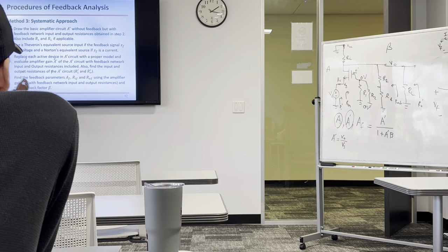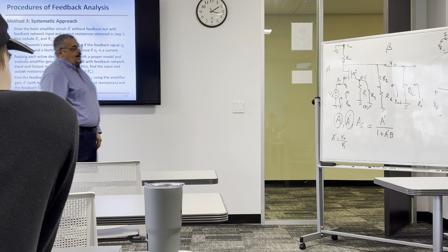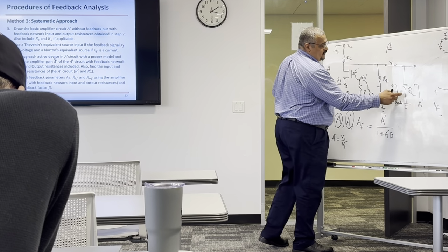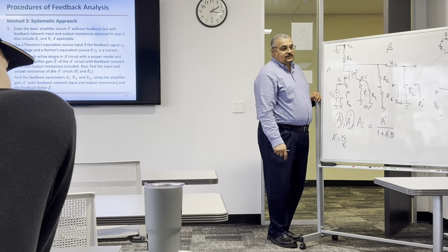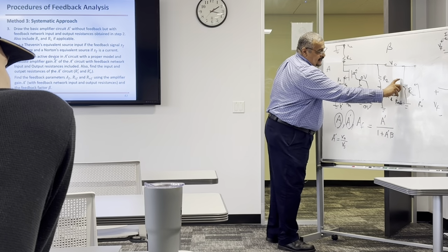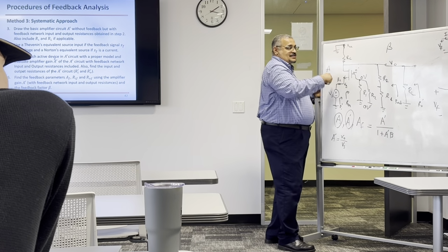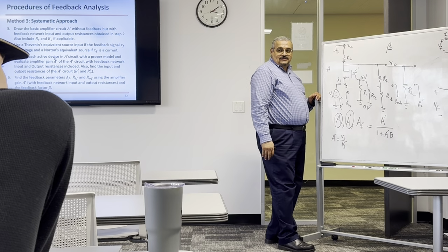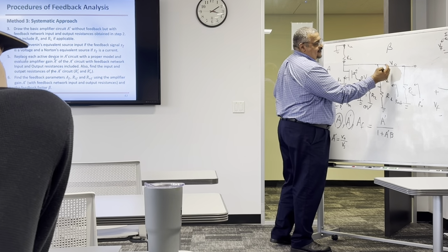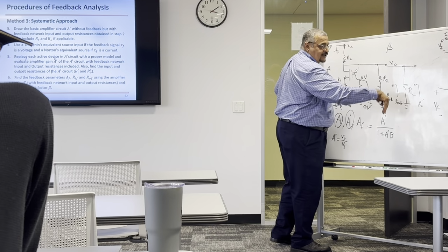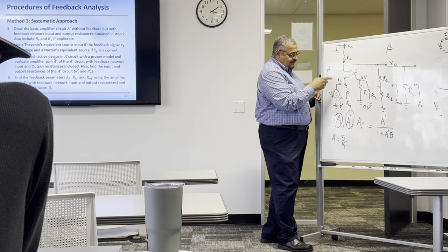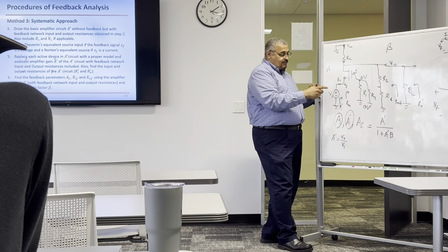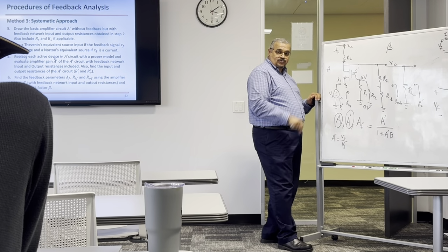If the circuit has RL and RS included in the calculation of A prime, meaning that if you have RL, what's the effect of RL in the circuit? When you calculate the amplifier, that will reduce the gain because RL, this series connection and RC, the three of them are going to be in parallel. So don't say, okay, I'm calculating the voltage gain up to this point without RL. No, include RL. Same thing for the RS. Don't say I'm calculating the gain from this point. No, calculate it from the overall gain, from the internal value of the source.